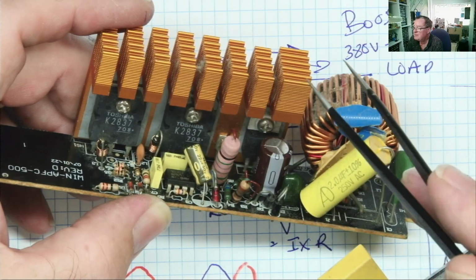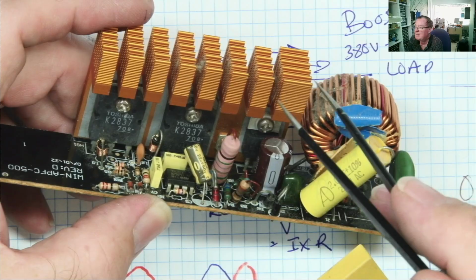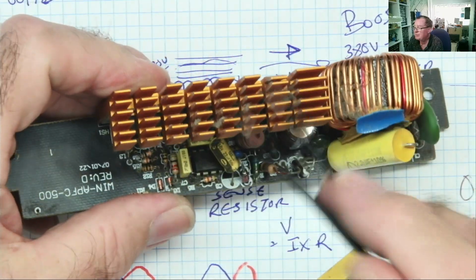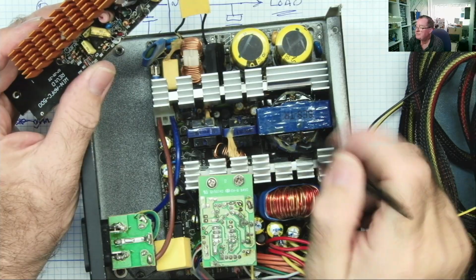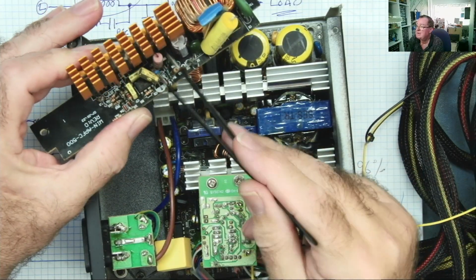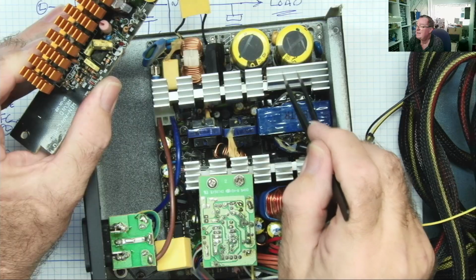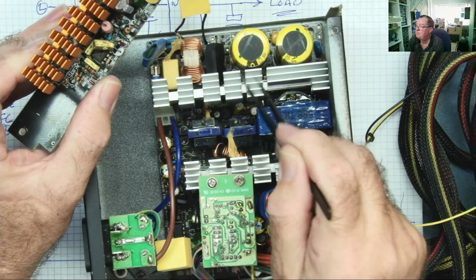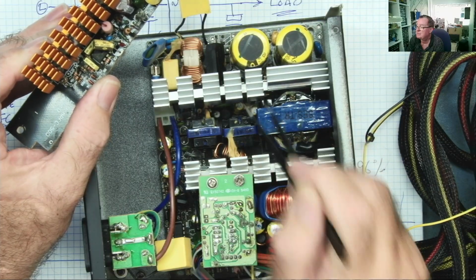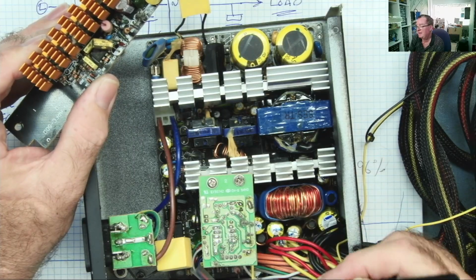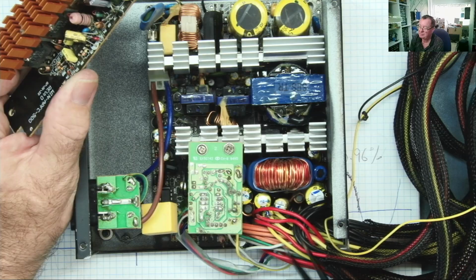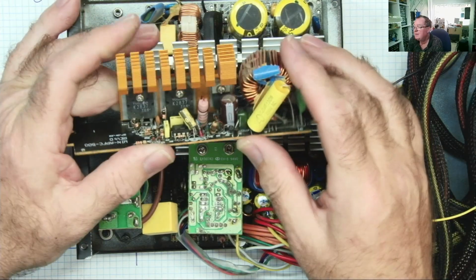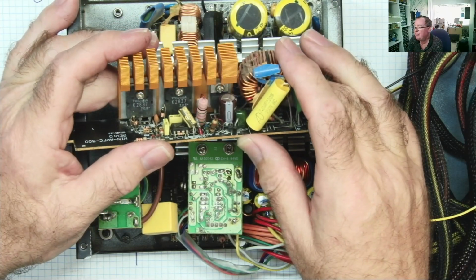You can usually tell with an ATX, at least, if it has PFC, active PFC, if there are three of these large heat sinks. They are usually all on the one PCB. This one is the PFC. This one is the switch mode power supply, the primary side, the switching transistors. And this one is the rectifiers on the output side. These are all your connections, 3.3, 5, 12 volts. Okay, so that's what PFC circuit actually looks like.